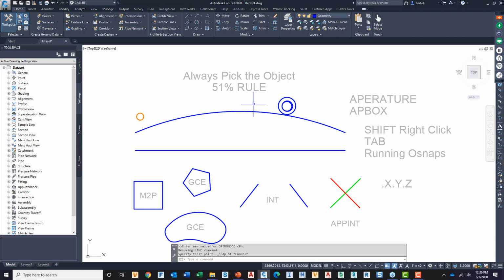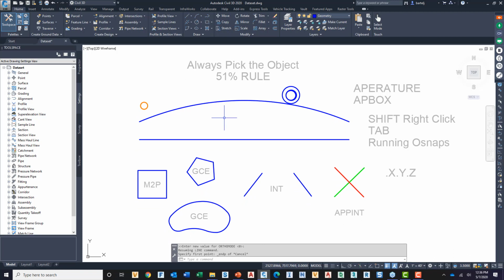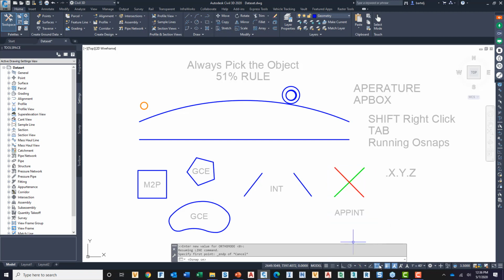Let's take a look at this. A couple of object snaps that we don't use on a regular basis, like we would maybe end and center in that. Let's turn on some running object snaps here, because I don't want to have to keep grabbing those constantly. My go-tos that I have primarily is endpoint, midpoint, center, node, and intersection. So I'm going to come down. We'll just lock those on for running object snaps for now. And let's take a look at a couple of the other ones.